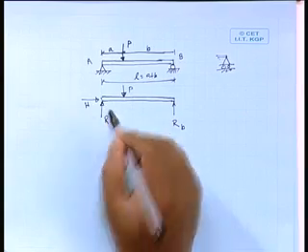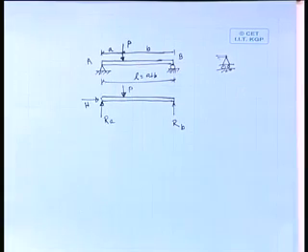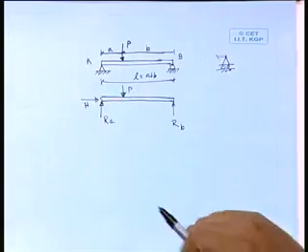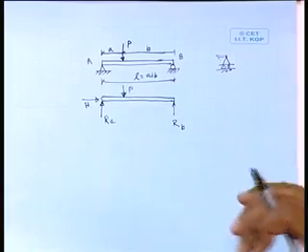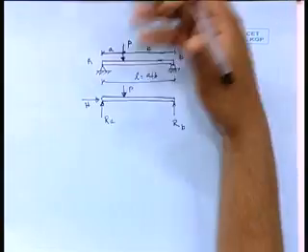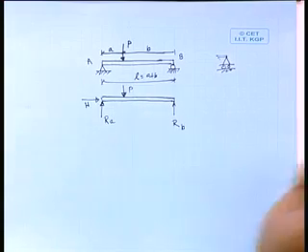We have the idea of the equations of statics. We know all the forces in a particular direction will sum to 0. So, the summation of all the forces along the horizontal direction we can take as 0, the summation of all the forces in the vertical direction as 0, or we can take the moment of all the forces about a point, and it should be 0. Normally, for a plane problem we have 3 equations of statics. So, from our knowledge of statics, we have 3 equations. Normally, we utilize those equations for finding out these reactions.